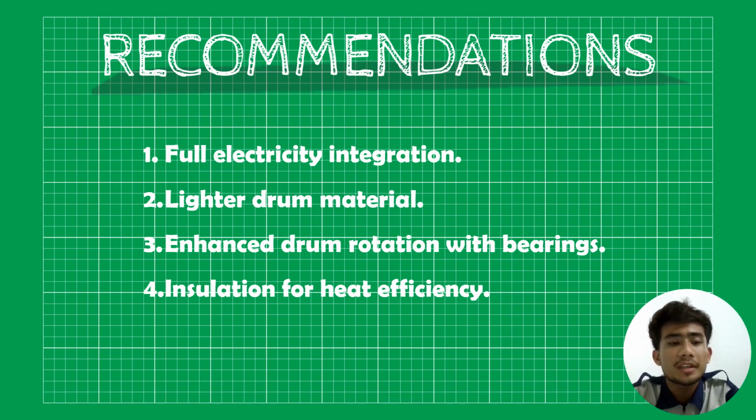As for the recommendations, there are four recommendations to upgrade the mini drum coffee roaster. The first one is to have a full electricity integration. This is to consider transitioning to a fully electric system for both roasting and drum rotation. This would involve using an electric heating element for roasting and an electric motor for drum rotation. This will allow for better temperature control and eliminate the need for an external stove, providing a more streamlined and